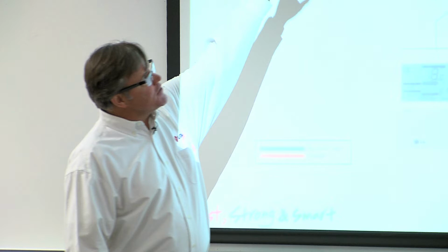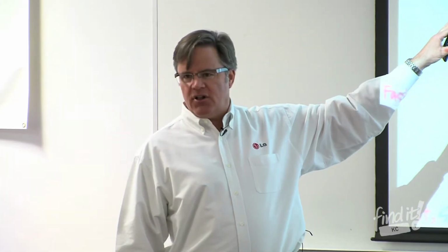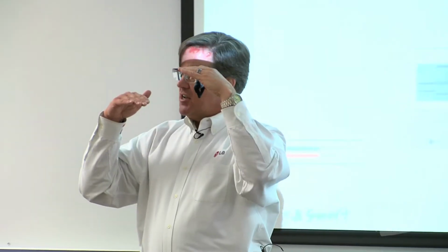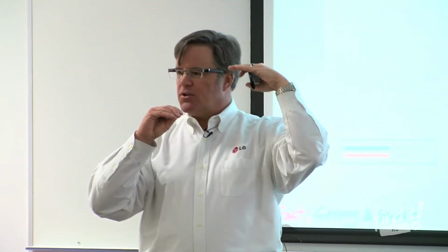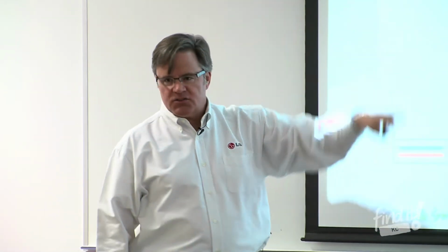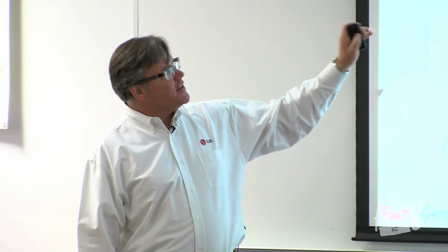So this is a heat pump system, and we have our glorified heat pump out there. We have several different indoor units connected to it in here, okay? And you see that we have two pipes running through all of it. Now, no matter what manufacturer you're talking about, this diagram is going to look exactly the same, okay? It's two pipes to all of them, and the choice between heating and cooling is made at the outdoor unit, okay? That means every one of these indoor units, while they can all have different set temperatures, maybe some guy wants it 65, the other guy wants it 70. If they're in heating, the guy that wants it 65, his valve just goes closed. The guy that's 70, his valve stays open until his room warms up, okay? And so that means that they all switch. It's like a two-pipe boiler chiller system, for those of you that are familiar with that. So that's a heat pump system.